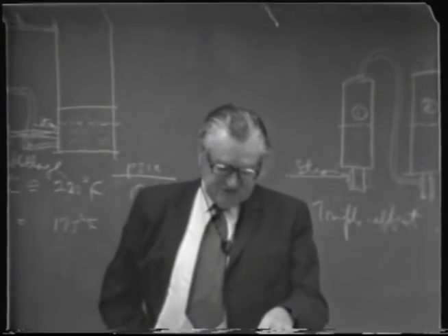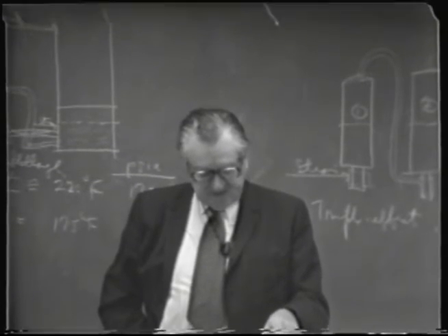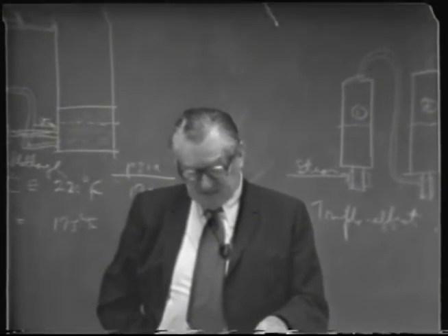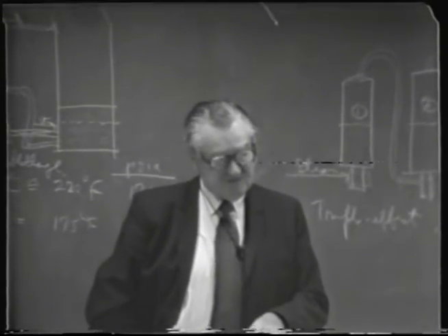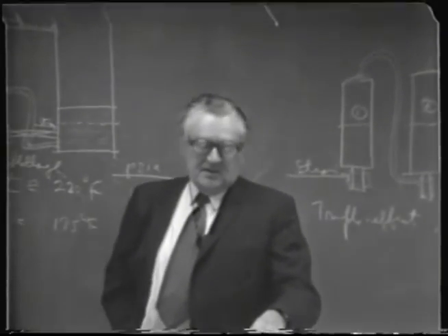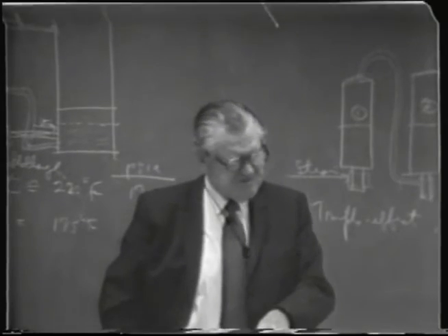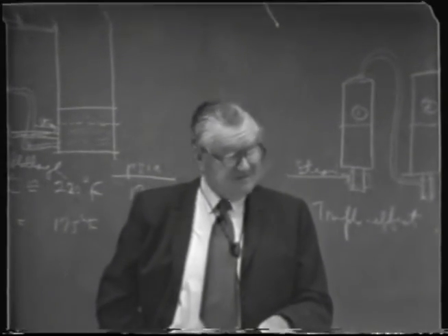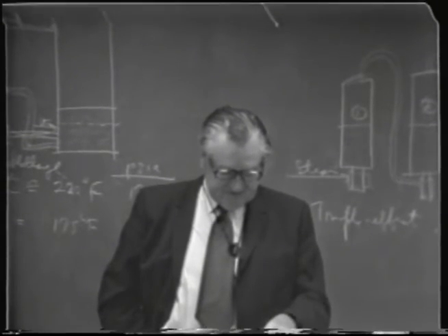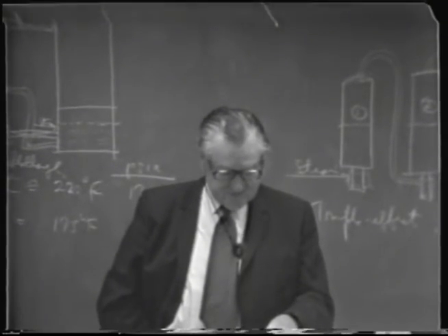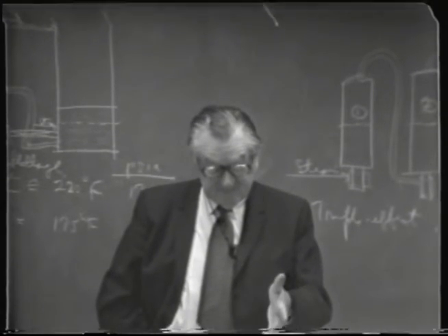There will be very little change in concentration under practical conditions of the alcohol from the material that's fed into this heads column compared to what comes out the bottom, because the volume of concentrated heads taken off is relatively small. Might be at the most 1% of the bottom product, something around order of magnitude. And so you could write a material balance and figure out what the proof of the bottom product was if you know the proof of the feed material and what the relative volumes of the top product and bottom product were.